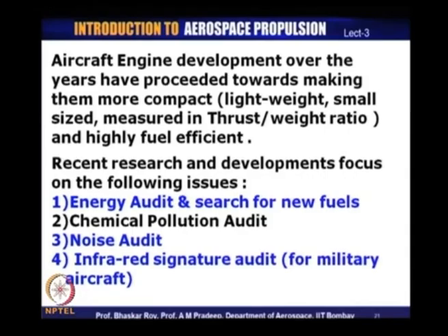The research that is going on these days tends to look at some of the new issues. We would need to have energy audit and search for new fuels in the coming years. We would need to have engines that create less pollution. We would need to have engines that create less noise, and there are lots of regulations in place these days about noise and pollution, and unless the engines conform to those regulations, they cannot be used or flown. For military aircraft, there is an additional requirement that quite often they need to have infrared signature devices, which would need to be installed in the engine.